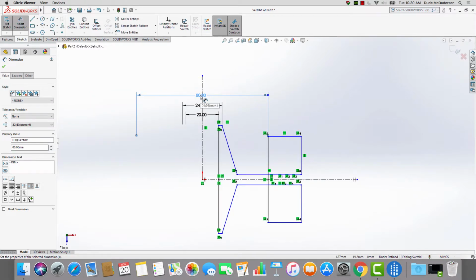All right, I put that value in. Now, you'll note what just happened. This will happen as you start to add dimensions to things. Your geometry may get inverted like we've seen here. You'll notice that it's no longer that solid gray interior because now we have a self-intersecting body, right? This line, when I gave it that dimension of 80, has moved over and shifted on the inside. The minute you see that happen, it's really important that you stop dimensioning and rewrite your geometry.